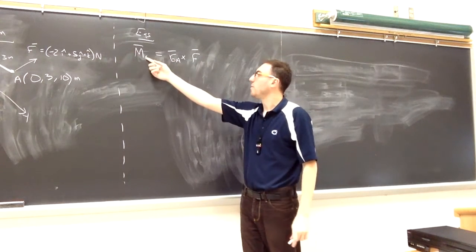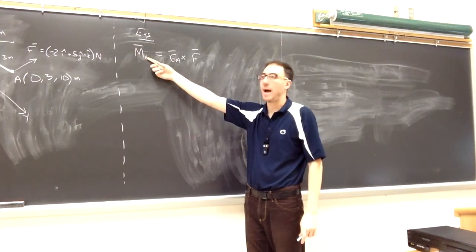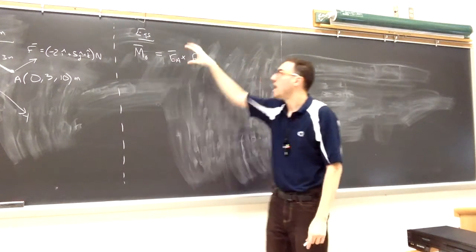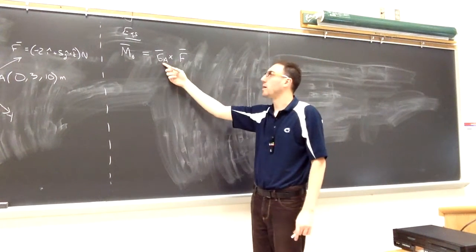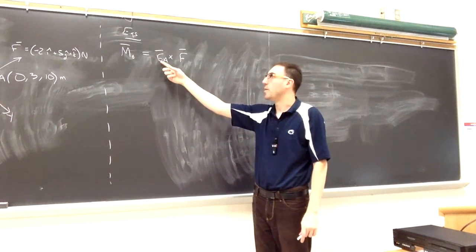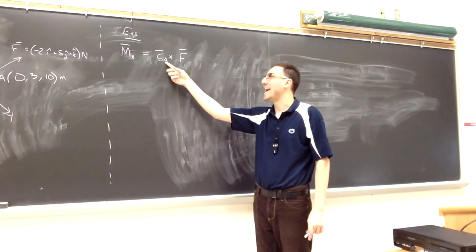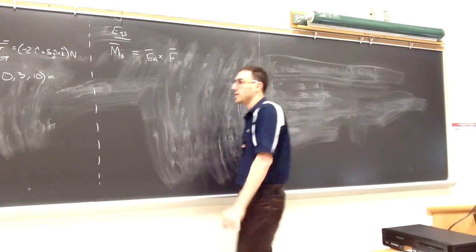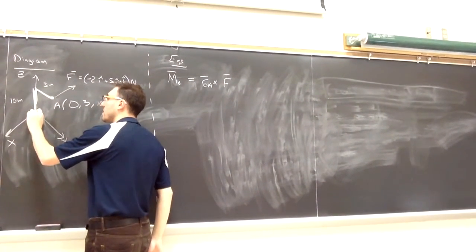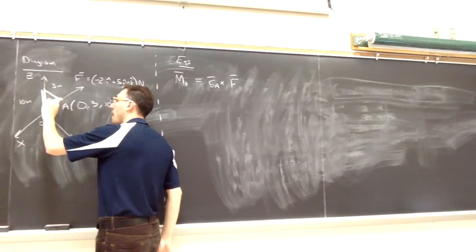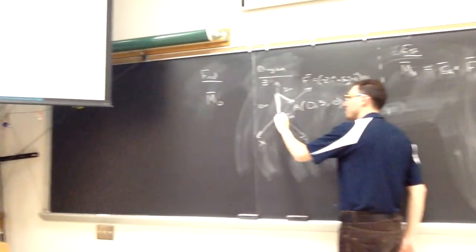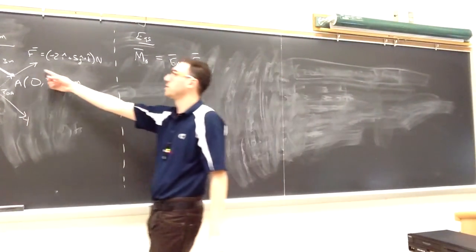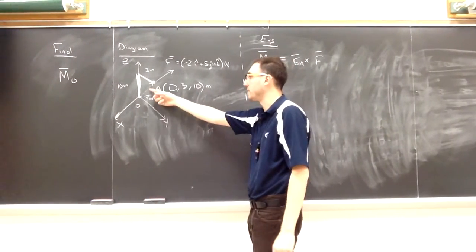It starts at O, because that's where we want to find the moment about. It ends at A, because that's where this force is being applied. If we have multiple forces, each one might be associated with a different position vector that will all start at O, but they will all end wherever their paired force is acting. So graphically, we could draw this vector in, goes from O and points towards A. So we're crossing this position with this force.